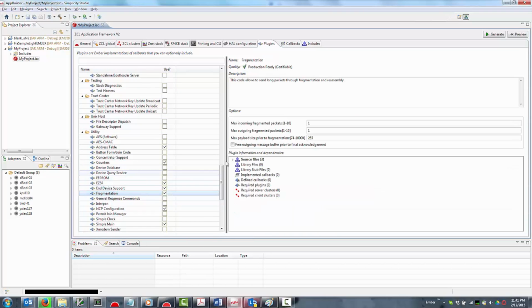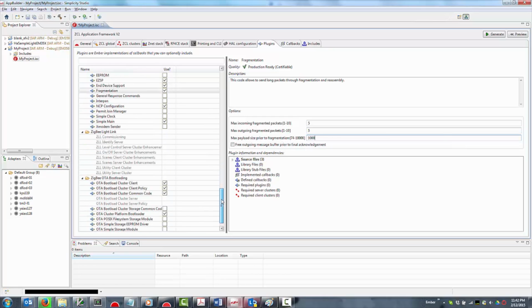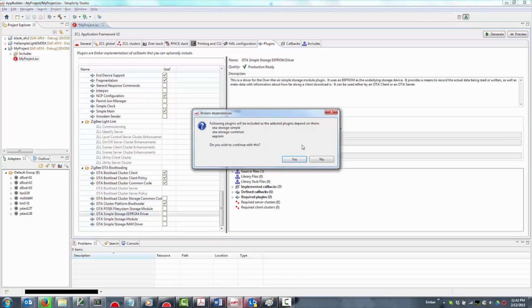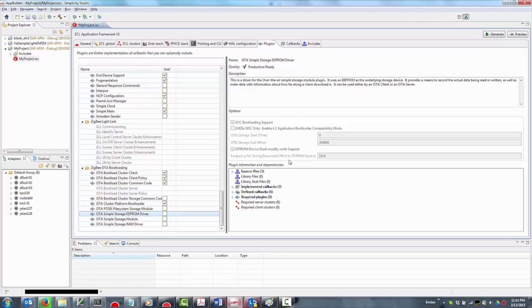Many plugins implement functionality for specific Zigbee ZCL clusters, such as level control, groups, or key establishment, so you can enable the plugin and in many cases get all the needed messaging required to pass Zigbee application layer compliance tests. Other plugins implement a software state machine and expect developers to integrate the hardware behavior into that state machine to get the device to physically react to changes in software state.